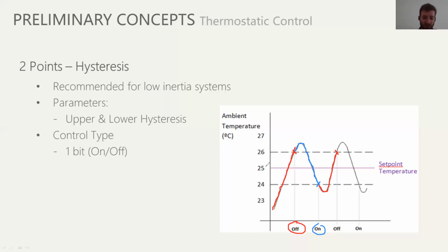So that's something you would define on the thermostat with 2 points, and then when configuring the fan coil unit or the AC unit, you would say, okay, if the temperature difference from set point to what I want to get is over 2 degrees, I want maximum fan speed. When it's just 1 degree difference, then I want to turn that fan speed low, to a minimum, for example, to medium level. But it's 2 different parts of the control. So, now we are focusing on the thermostat control. So the thermostat will just send turn on, turn off, turn on, turn off in 1 bit.